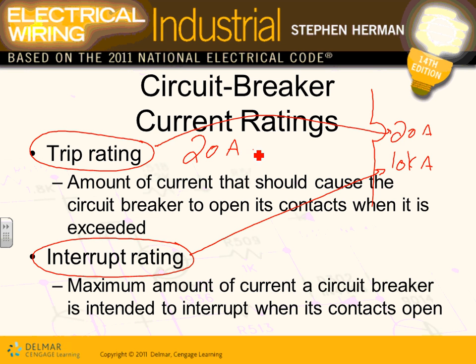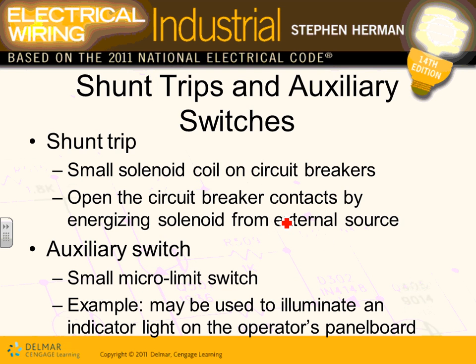Here's another: you can have a 2000 amp breaker and the interrupting rating for this guy, say 65,000 amp. That's how much short circuit this circuit breaker can handle. Comments, guys, about the interrupting rating versus the trip rating? Cool. So that's interrupting and trip.